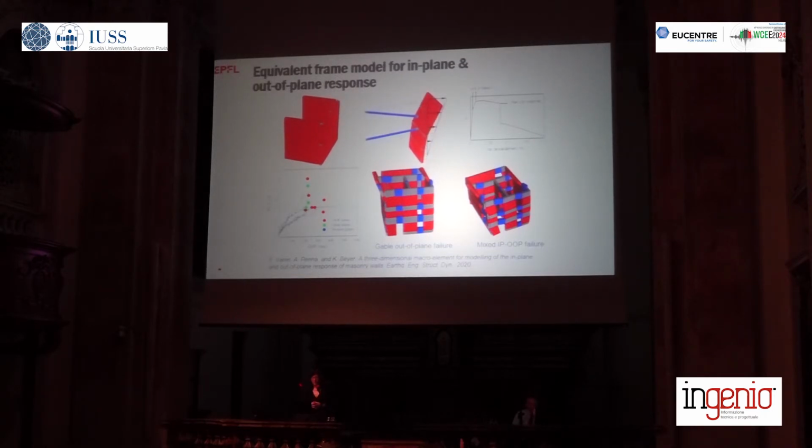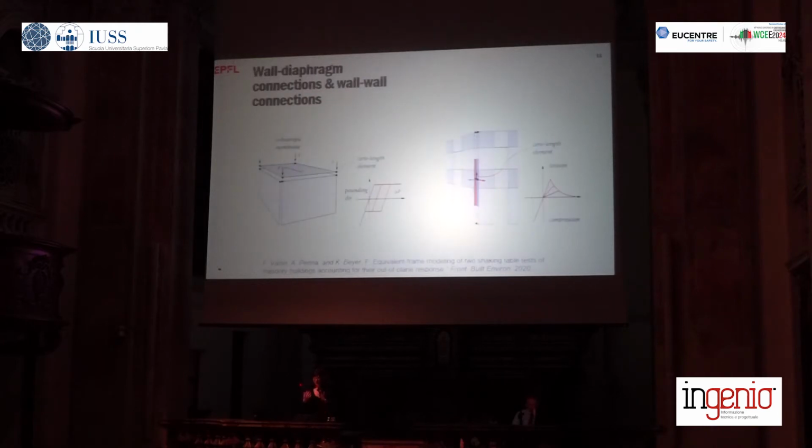If we include the out-of-plane behavior, then we can do, for example, incremental dynamic analysis, and for some ground motions it will fail in plane, and for some others it will fail out of plane, and we really can bring the two analysis streams together. As I just said, if you want to capture out-of-plane behavior, we really need to model also the nonlinearity of the connection, in particular of the wall diaphragm connection, but also of the wall connection. This we do with nonlinear springs. And all these models have been implemented in OpenSees, which we basically use as our basis.